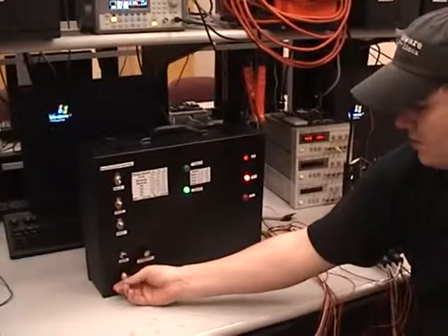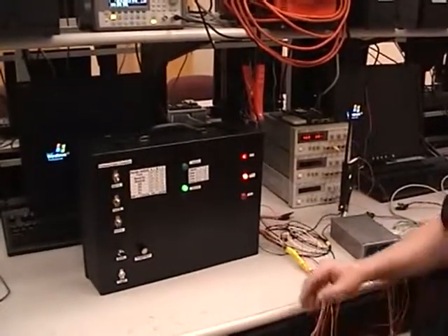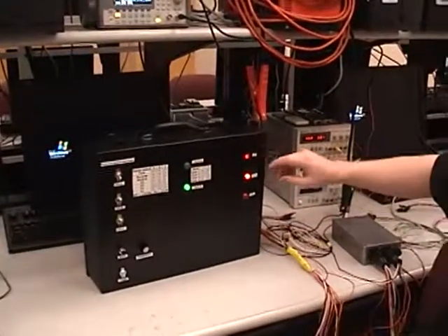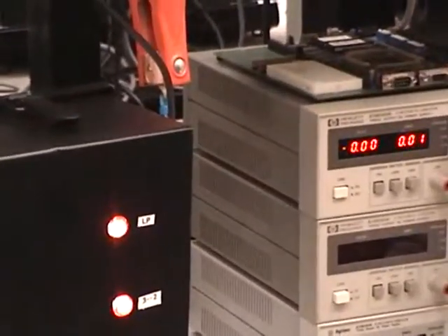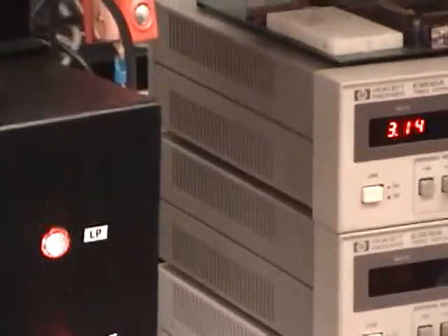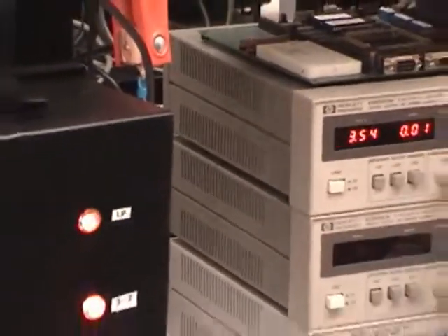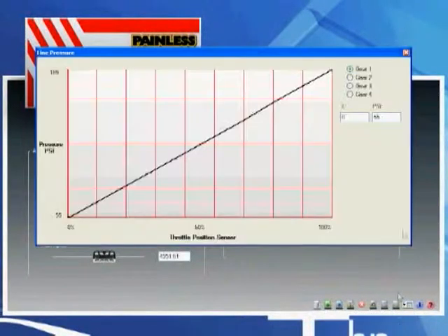So we can also show you right there that we can access two different settings. Your line pressure right here, you might have noticed that this light was dimming and brightening as I was messing with the TPS. And again, that's your line pressure, and it's directly related to the TPS. The user is able to configure the line pressure to react however they desire to the throttle position.